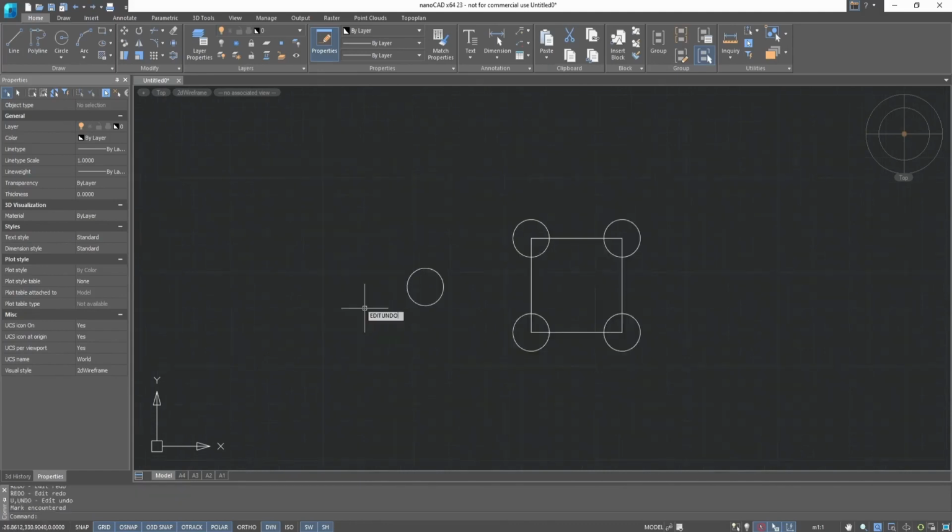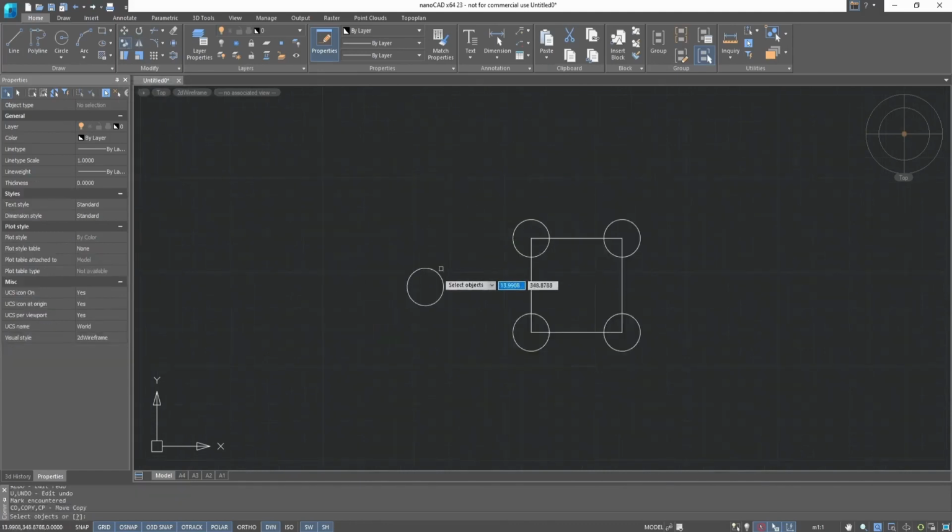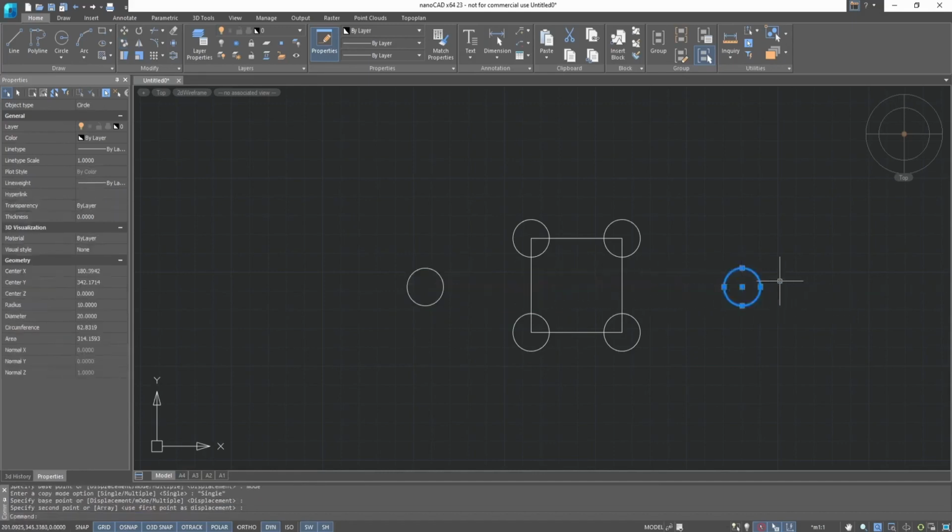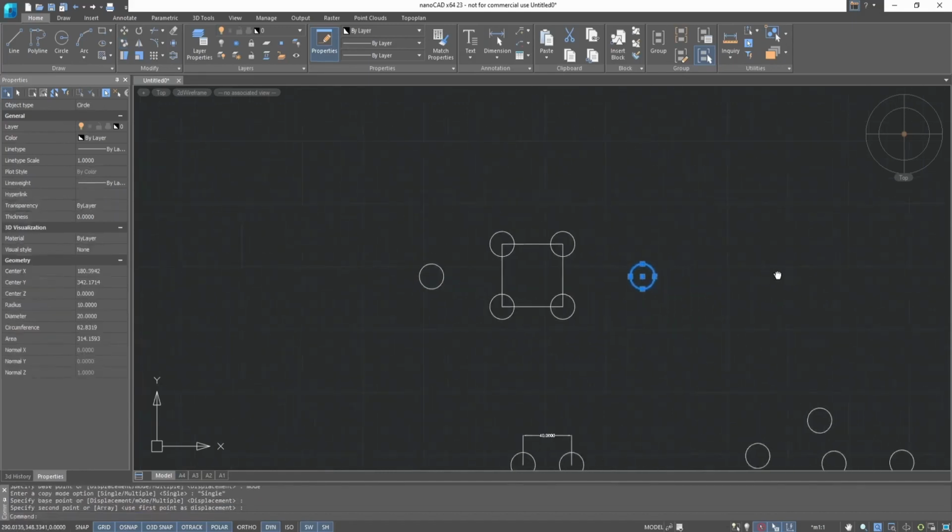We'll call the MoveCopy command, select the object, and then move to the mode option. This option suggests copying in a single mode, or multiple objects for copying. We can use the single mode and see what it entails. We see that the copying does not continue. This is convenient if you need to copy an object only once.